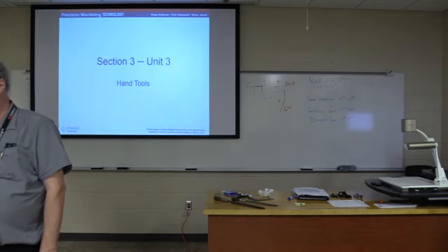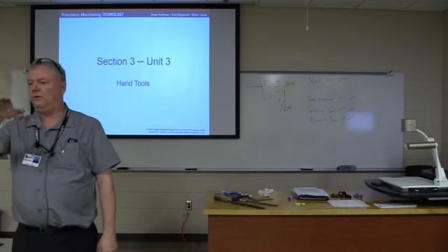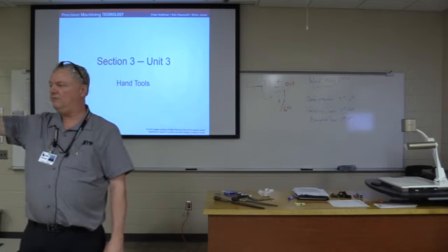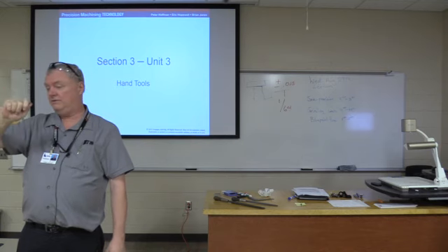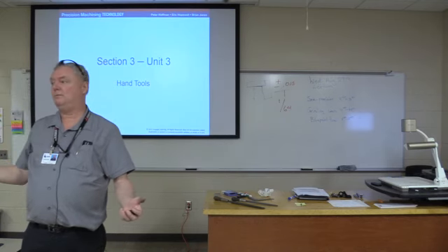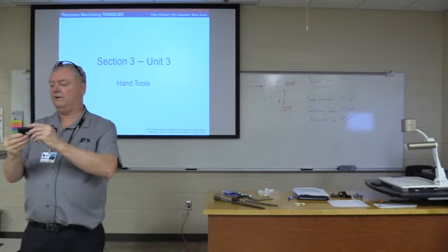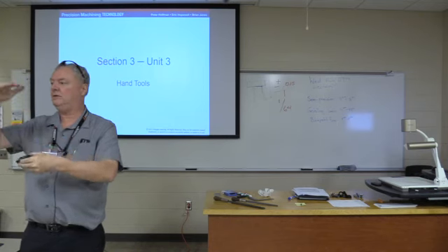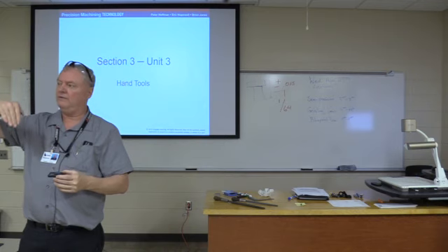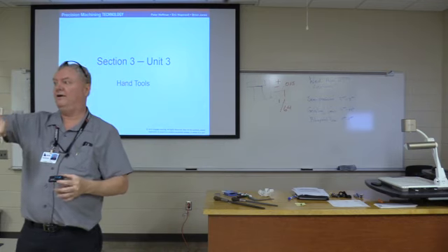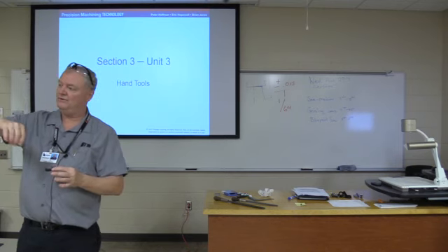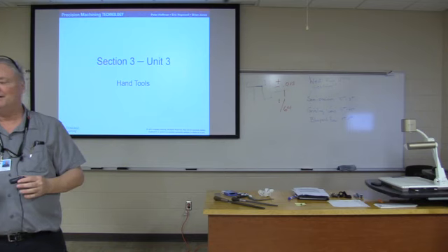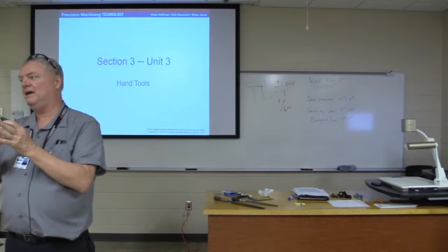And as in all things, when you're doing work that is of a complex nature where many different assemblies are involved, especially with dies and molds, there's always going to be massaging of a part. If you're dealing with a mold that has a free form flow going from one set to the other, the upper and lower die halves, you usually have to hand file it, because consumer products being what they are, they wouldn't tolerate seeing a plastic seam in between your two mold halves. So you're going to be in there with what's called a die file or a die grinder, and it's a very fine piece of handiwork that you do, because it doesn't always come off perfectly matched.